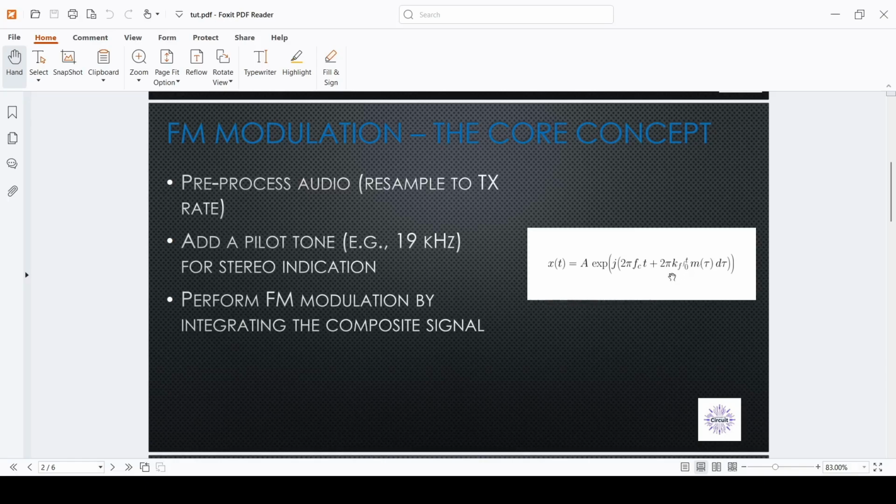I'm going to show what down and up sampling essentially mean mathematically, but essentially we are going to add more data points to our data so that in smaller time spans we have more information. The way that we do it is adding zeros after each data point to match the sampling rate.